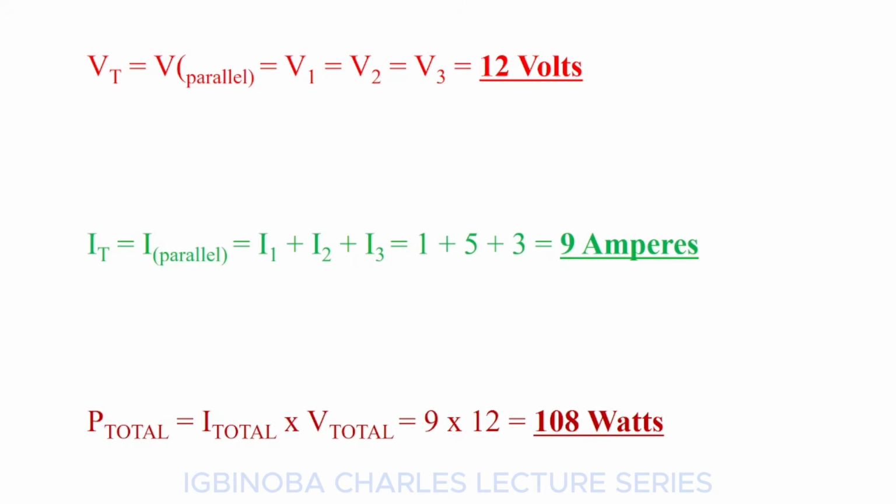While our simple example has a nominal current of 9 amps as we see here, at maximum power it could potentially be higher at 9.9 amps, that is 9 amps times 1.1, which equals 9.9 amps. It is this higher current value which needs to be considered when installing cable between parallel connected panels and DC load, so that there will not be burn in the system.